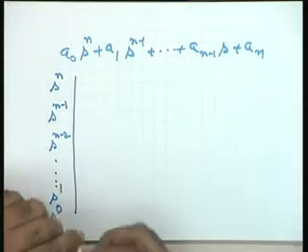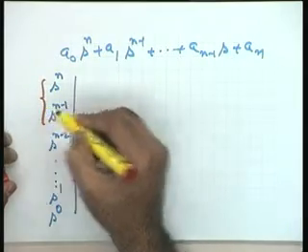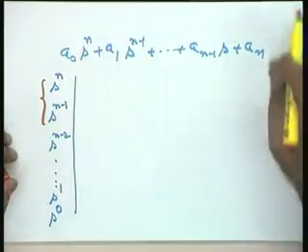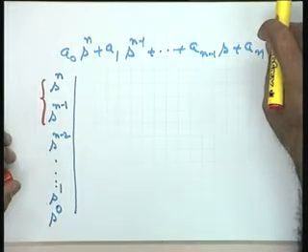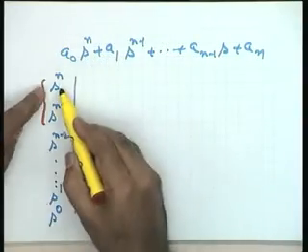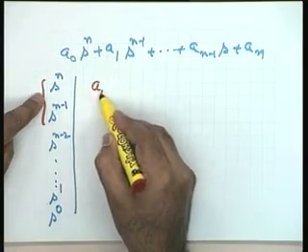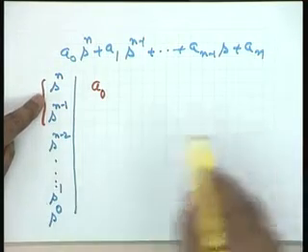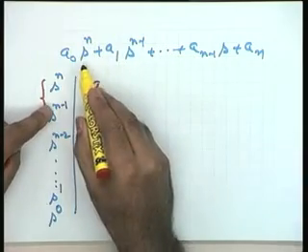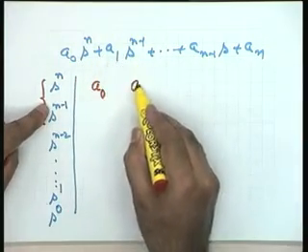Okay. The first two rows are given to you, and the coefficients of these first two rows are given by this characteristic equation. How do we write these rows? Please see it very carefully. S to the power of n, first coefficient is a naught. So, write the first coefficient here, it is a naught. Then, leaving one coefficient, after a1 it is a2.